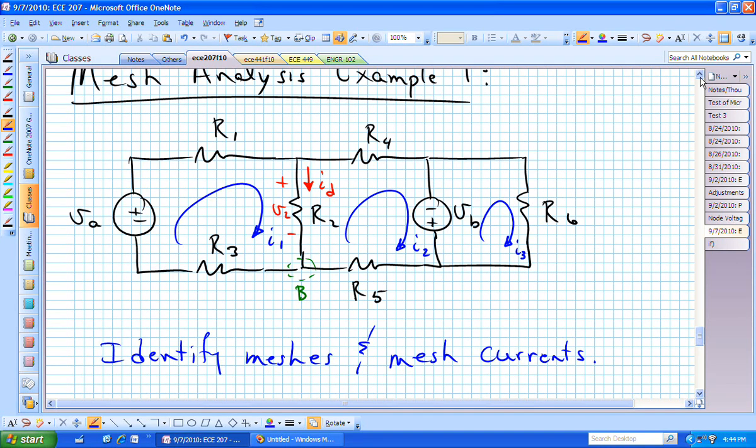The point I'm trying to make, which I'll go ahead and release you after I make this comment, is that I sub d is made up of I sub 1 and I sub 2. You just need to figure out how it's made up of those and get the sign correct. The easiest way, I think, is to visualize and say I sub d is being helped by I sub 1, so that must be positive. It's being hurt by I sub 2, that's negative. So I sub d is I1 minus I2. We'll pick up at that point on Thursday.